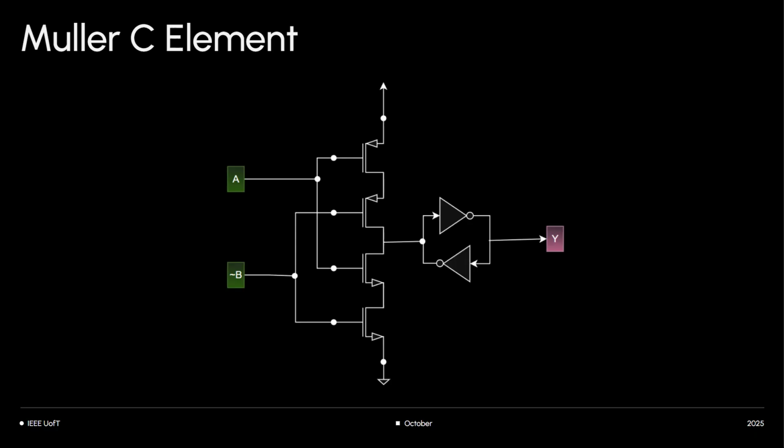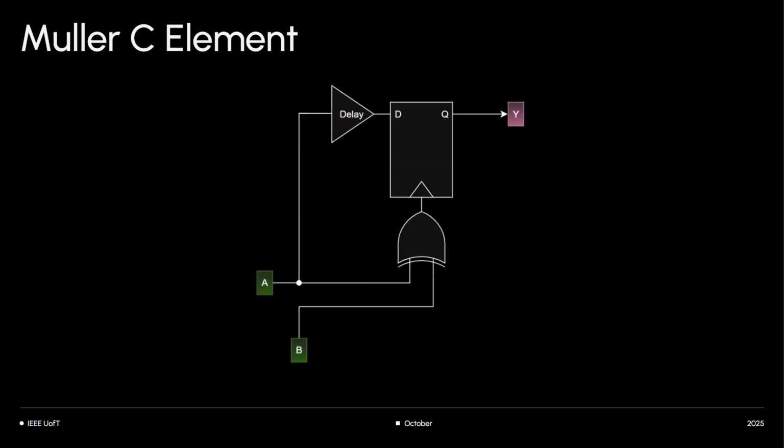If you work out the truth table for this, it will work out. Okay, can someone tell me this? It should be fairly straightforward. What is this inverter loop you see here? Oh, sorry. Whenever there's a loop, what did I tell you before in the starting of the meeting? It's storing information, right? So essentially, this is a simple implementation of a memory. It's not a flip flop.